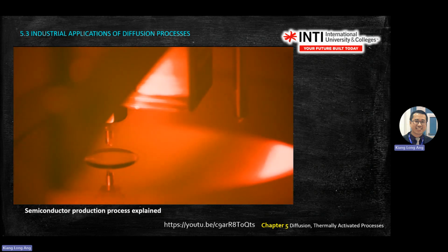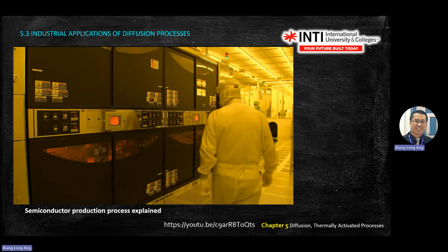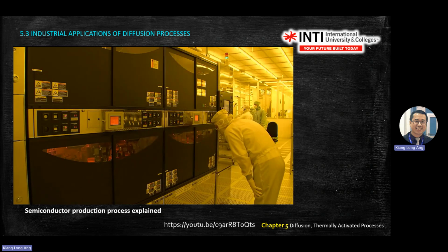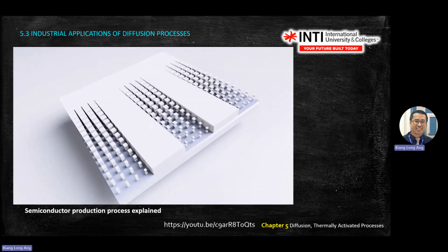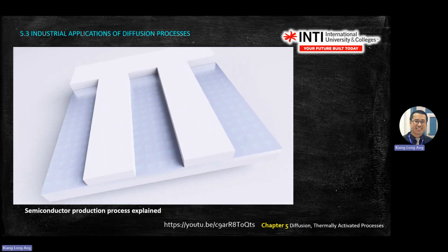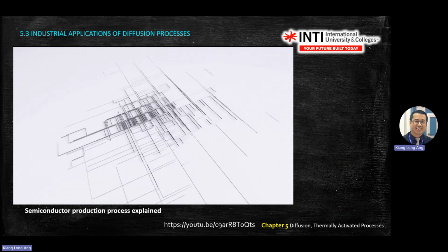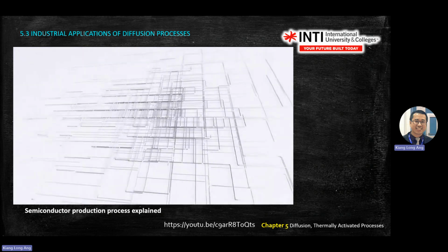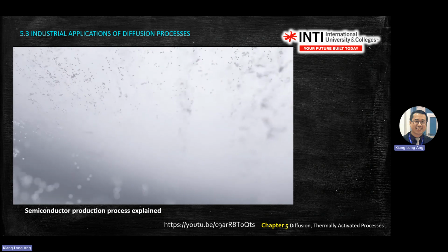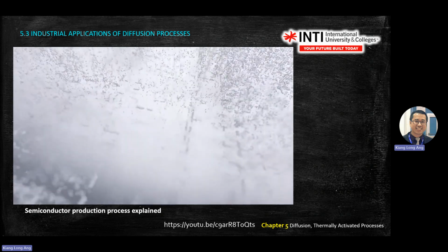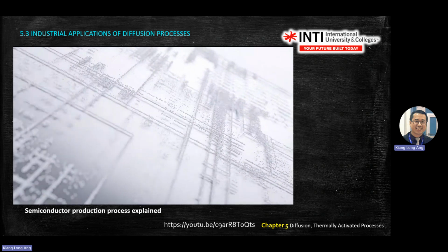After coating with a photoresist layer, the wafer surface is exposed, developed, and etched. This results in the desired conductor structure. Such structures are hundreds of times finer than a human hair. Dopants are then implanted in the material to increase the electrical connectivity of parts of the semiconductor.